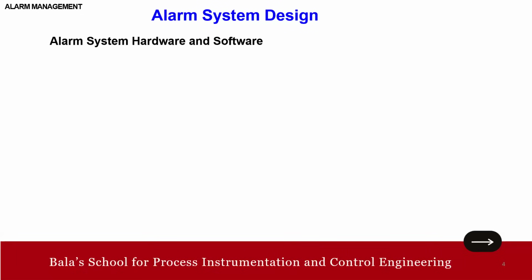Then we go into the alarm system hardware and software. Maybe before going into the detail, some of the components that make up the alarm system will have other uses or be provided almost by default. In particular, the sensors that measure conditions, the transmission mechanism, meaning cable, and the devices that receive the data are likely to be part of the BPCS and SIS. So here the hardware and software used to communicate alarms to the operator are of most interest and need to be optimized through design.